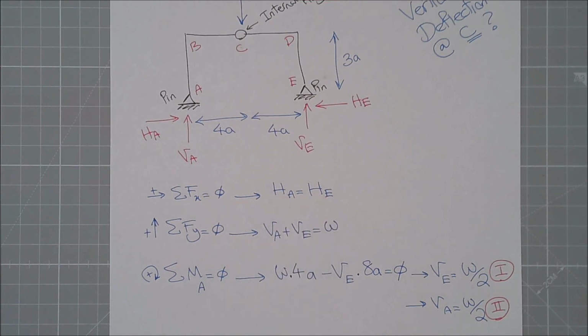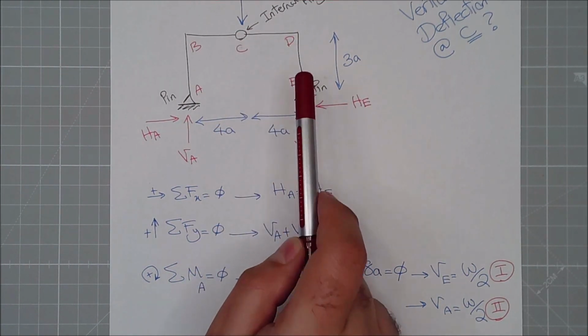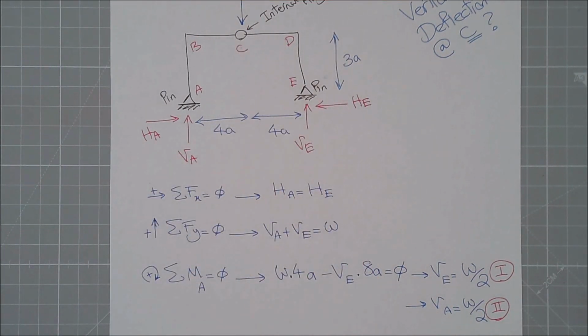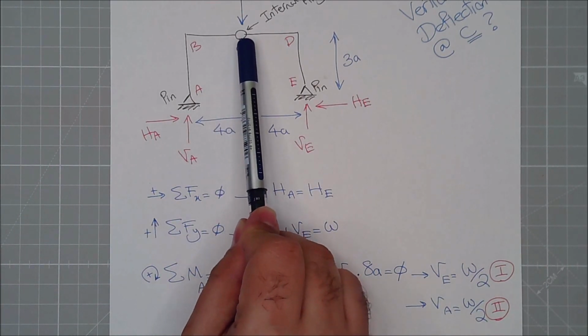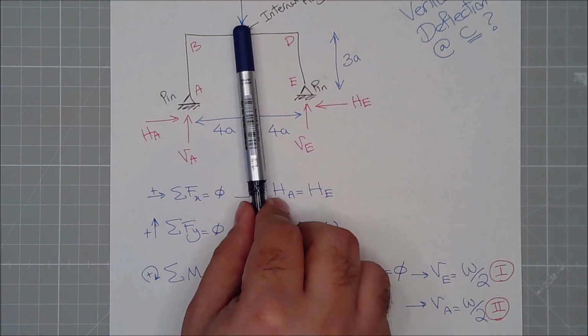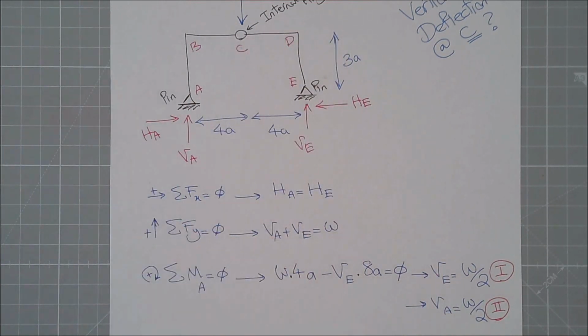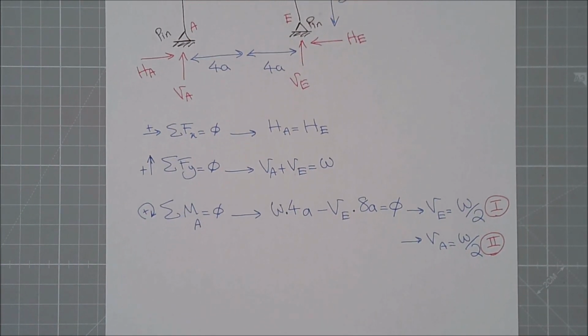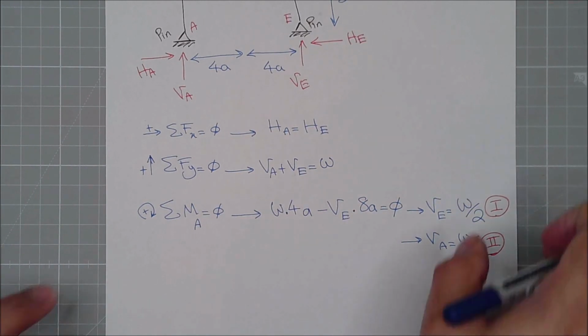Still haven't figured out these guys. The good thing is I have a hinge, so I can cut one side and write one single more moment equation as well, because this hinge in the middle omits the moments going around, so I can consider this side as a separate side from the other side. So let's see. Let's draw it first.